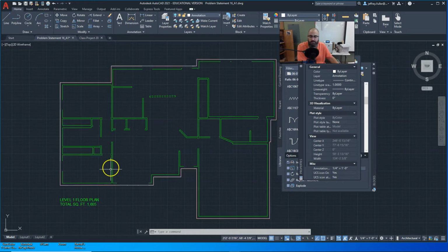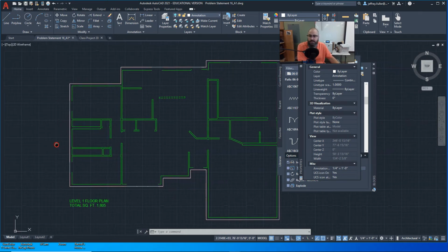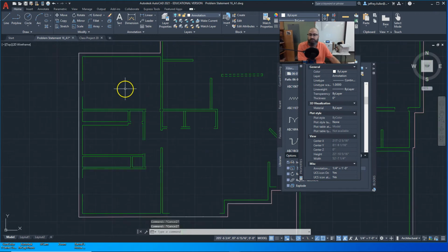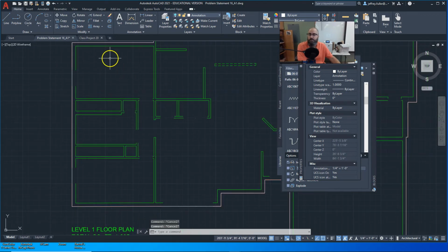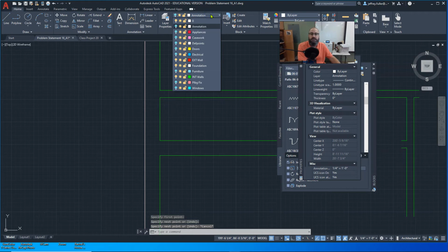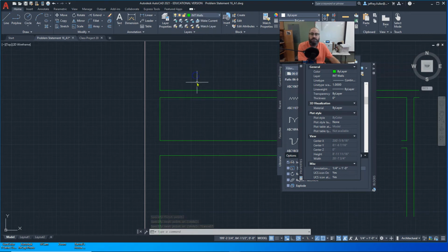Now, an engineer would probably also make this wall load-bearing, maybe, or maybe this one also. Okay, but just so we get practice at drafting a load-bearing wall, we're going to just do it on this one. And to get a good center of that wall, I'm going to click on the line tool, and I'm just going to draw right through here. So that's one little line, and I need to be on the interior wall layer.